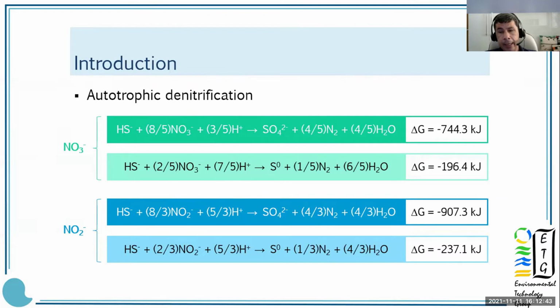And the idea is to see the different concentrations of sulfate and therefore sulfide formed, and also in terms of nitrite and nitrate concentration, to see the best combination of strategies together with microaeration to produce a system capable of removing both fractions of sulfide.